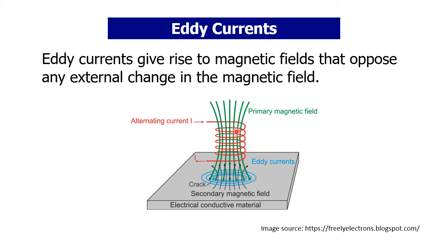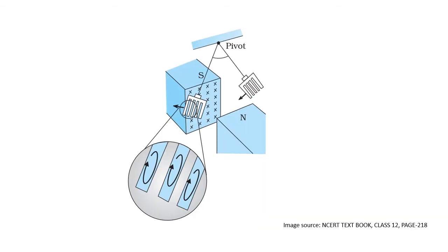Here magnetic flux is hitting the conductor surface, so from the conductor, magnetic field will be generated. Eddy currents will develop and magnetic flux will generate in the opposite direction to compensate the increase in flux crossing the conductor. So this is the concept of eddy current, which you can see in the diagram also. For example, if you cut the conductor like this and move it, whenever it is coming out of the field according to this position, you can see the eddy in the clockwise direction.